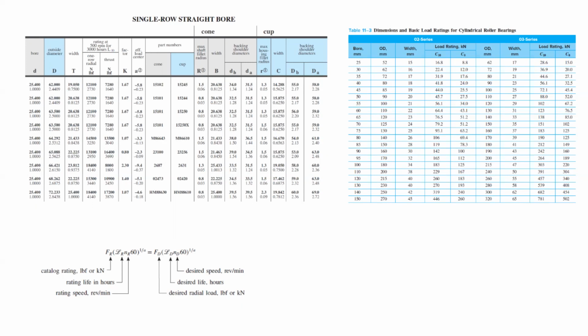Okay, so we start there, and you have some minimum amount of size that you need to stay under. So you can typically select the radius of the bearing first, and that's the first thing you do. The second thing you should ask is, what kind of loads do I need my bearing to support at static? For the wheel, that's pretty simple. You have a moment load that originates from the peak normal load that you expect on the wheel, but you also have these lateral loads that push on the tire and these longitudinal loads. So you can see that even though the bearing only has three basic loads, radial, axial, and moment loads, the way that they manifest from the loading conditions on your system can be pretty complicated.